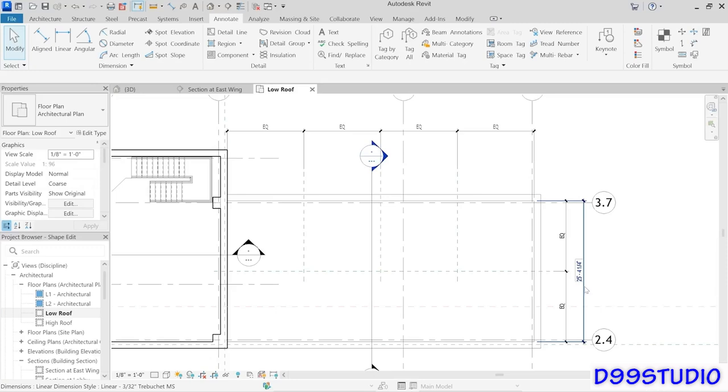So that's our total distance that we want to slope. So we want to pitch the roof down along that distance. So what we need to do is calculate how far we want this slope to be. Now, as I mentioned earlier, there's usually a building code that determines this. Most of the building codes that I'm familiar with have a minimum slope of 1/4 inch for every 12 inches of run. That would translate to about 6¼ millimeters for every 300 millimeters of run. And that's the value that I'm going to be using for my calculations. But if your jurisdiction calls for a different slope, then feel free to use different numbers.